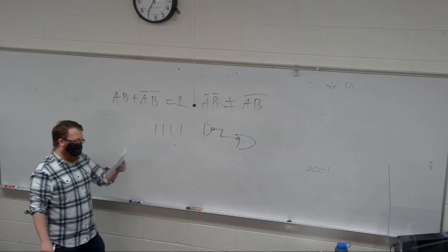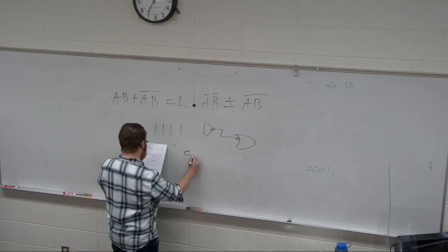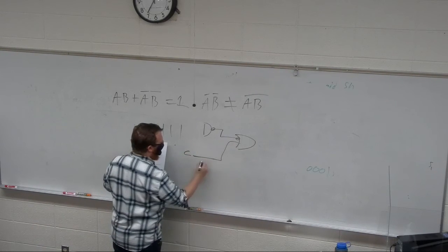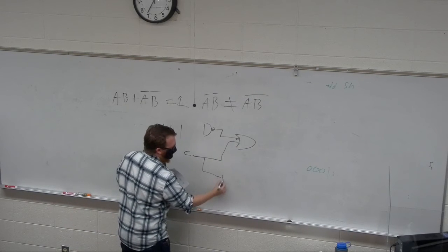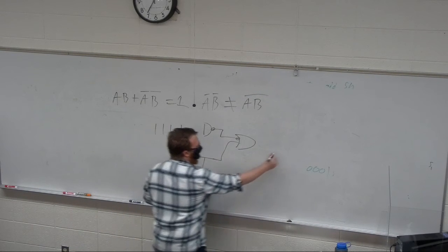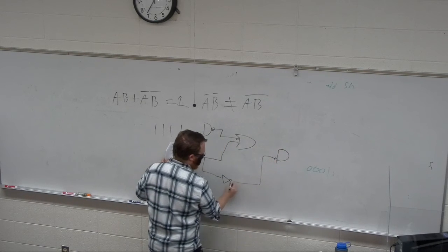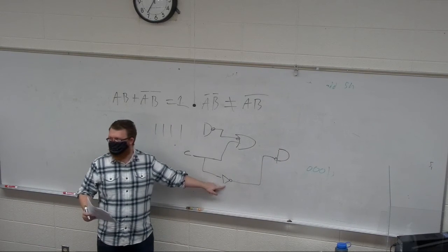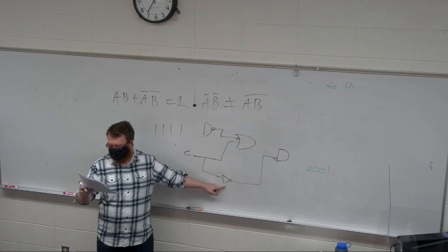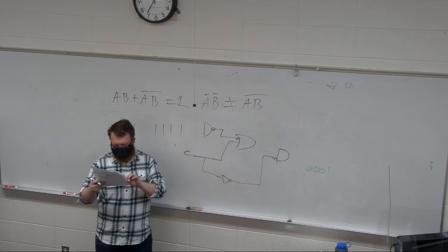The only tricky one on that really was that you have the C branch that goes into an OR gate and then comes here. A lot of you missed that it needs an inverter if the AND gate, or OR gate, whatever it was, gets a bubble. I need to then do something with a bubble, right? I need to re-invert it. So that was the only real common mistake I think I saw on that one. And part A was good.